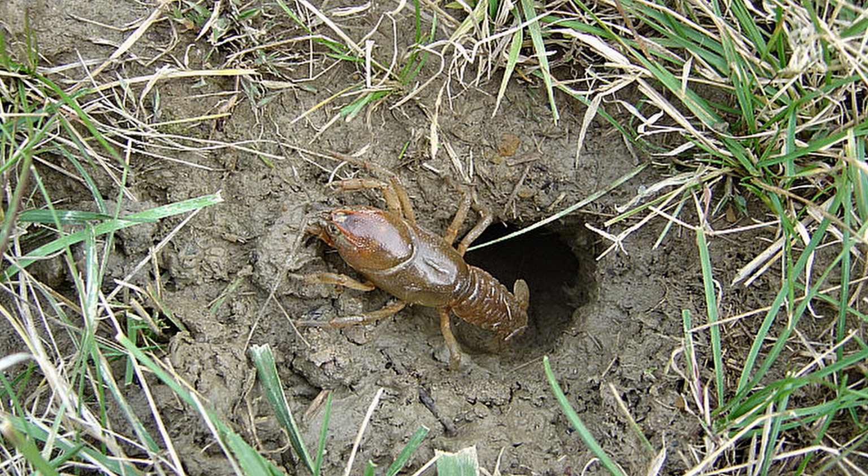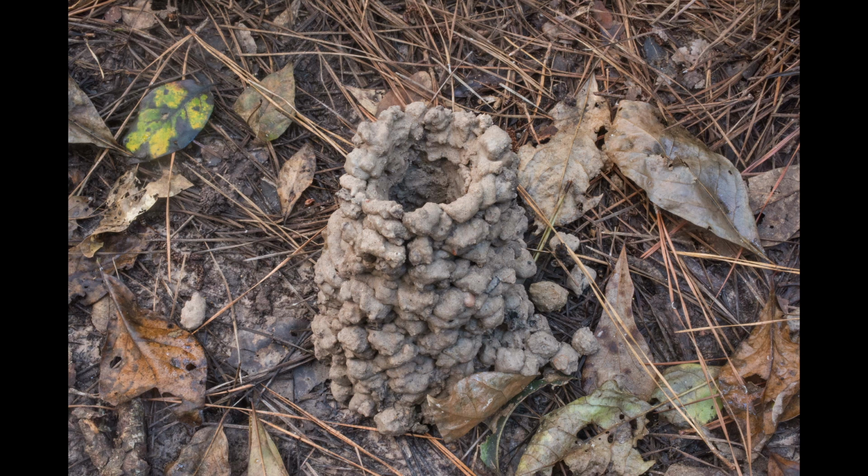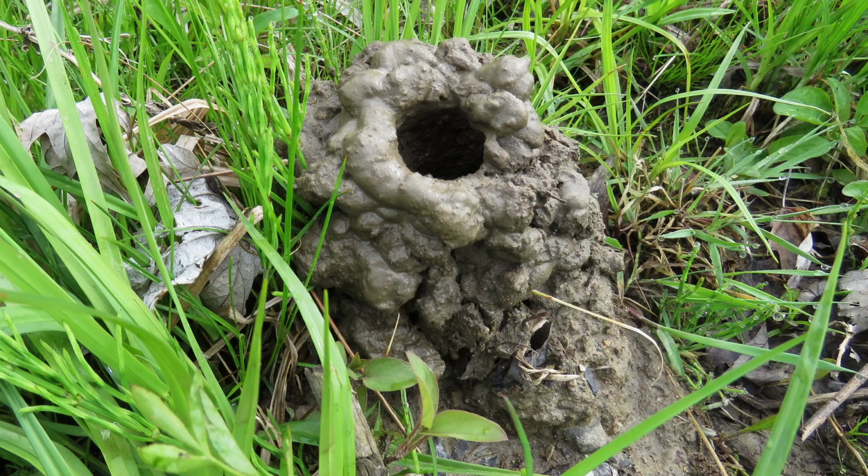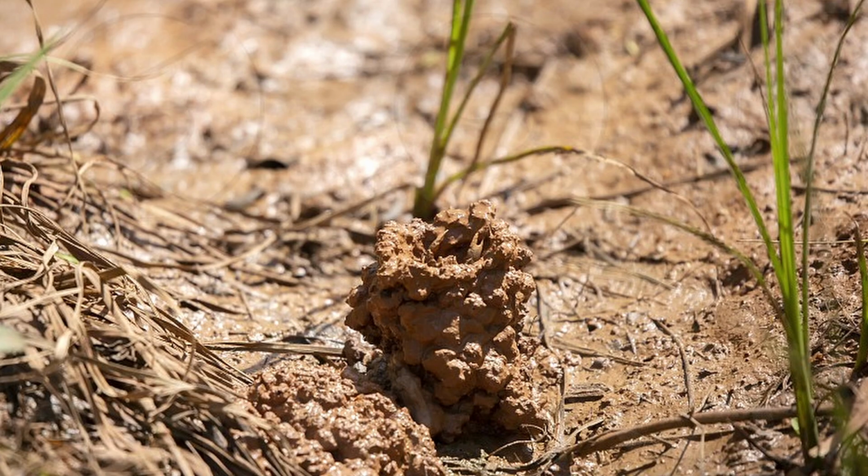The diameter of the crayfish holes averaged 1.5 inches, with an average area of each hole being 1.76 square inches. Crayfish holes were typically spaced 32 inches apart, and this yields an average of 6,000 burrows per acre at the Dix River site. It was estimated that half of the burrows terminated in the gravel, which meant that the burrows had the same effect as an open 7-inch diameter drain pipe for every acre of wetland that would be restored.